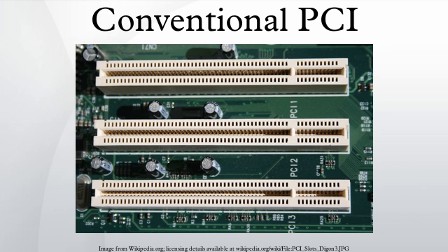full-size card. Half-length full-height card: a half-length full-height card has a length of up to 175.26 mm and a height of up to 107 mm. The actual dimensions of many cards described as half-length full height are lower than these maximums, and they will still fit any standard full-height PCI slot as long as they use a properly located full-height bracket. This is in fact the practical standard now. The majority of modern PCI cards fit inside this envelope.